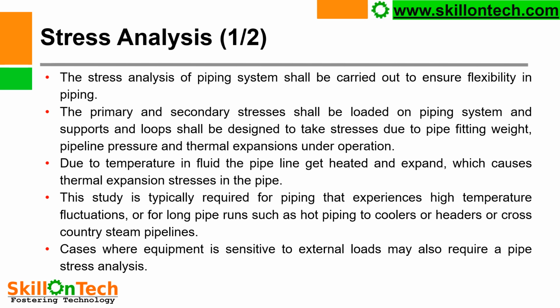If we do not do stress analysis of the pipeline, then during commissioning of the pipeline, your supports will be damaged. Your pipeline can be damaged because the unwanted stresses will block your pipeline and supports. Due to temperature and fluid, the pipeline gets heated and expands, which causes thermal expansion stresses in the pipe.